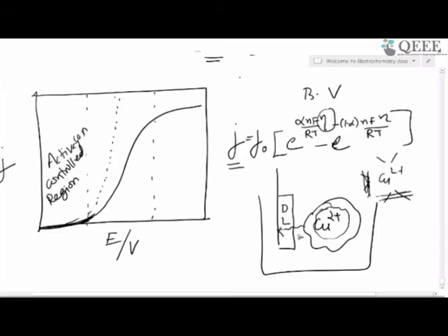This ion will do that by taking energy from the available energy of the battery. That means the voltage of the battery will drop. This drop in voltage, when no current is flowing, is because that energy is taken for removing or redesigning the hydration shell so that it can reach the electrode surface. So it's called the activation controlled region.